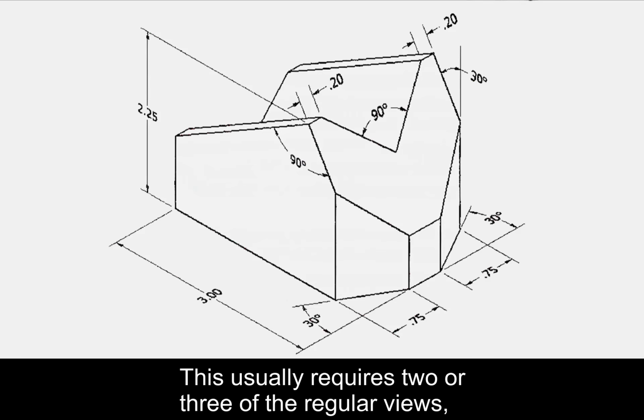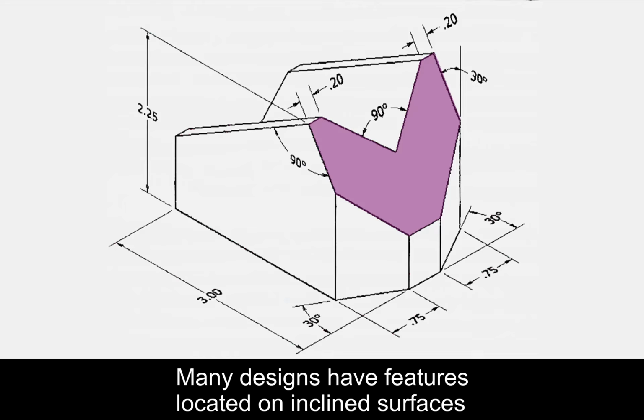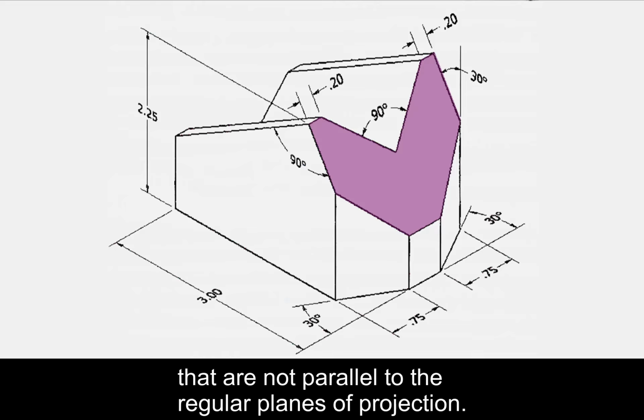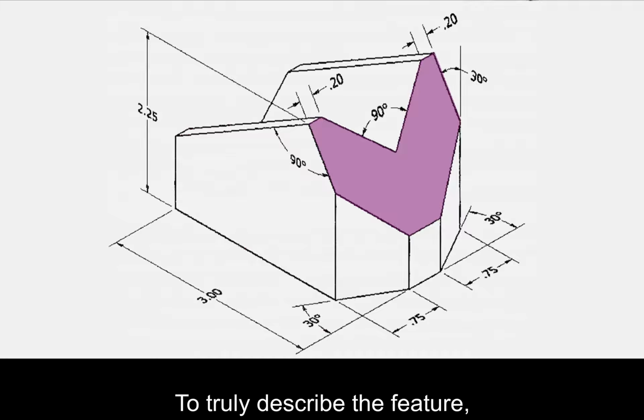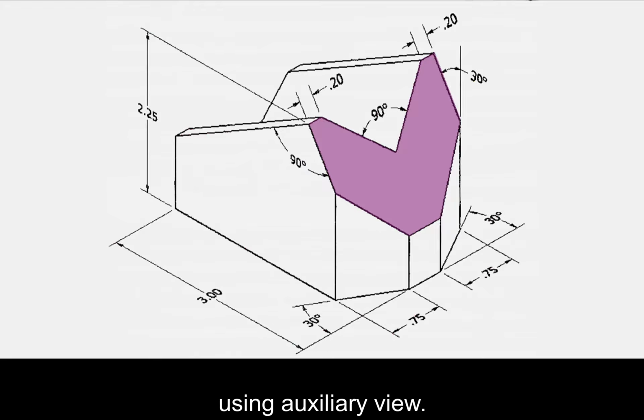This usually requires 2 or 3 of the regular views, such as a front view, a top view, and a side view. Many designs have features located on inclined surfaces that are not parallel to the regular planes of projection. To truly describe the feature, the true shape of the feature must be shown using an auxiliary view.